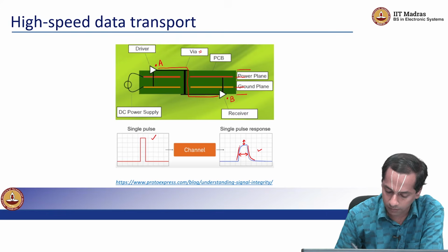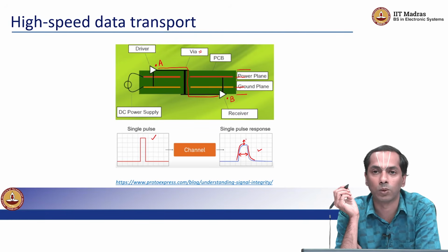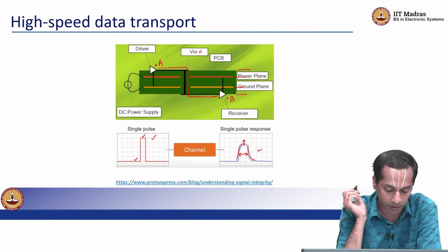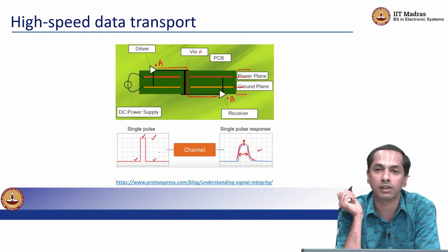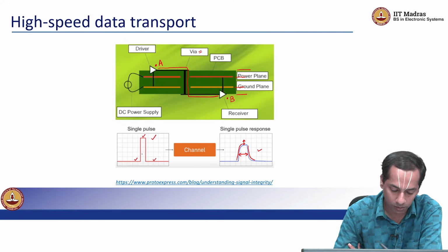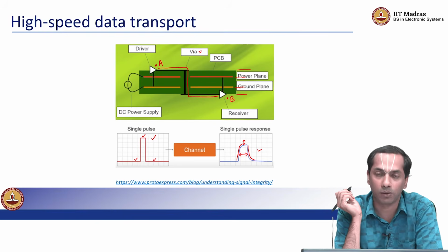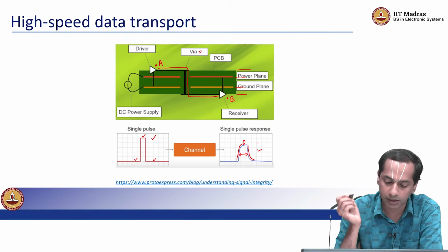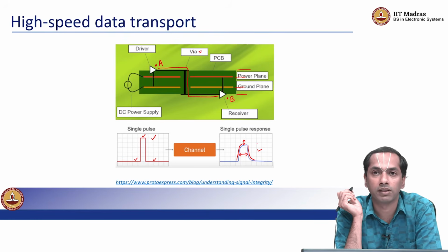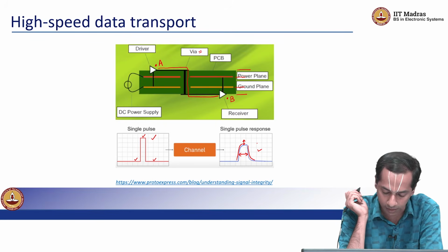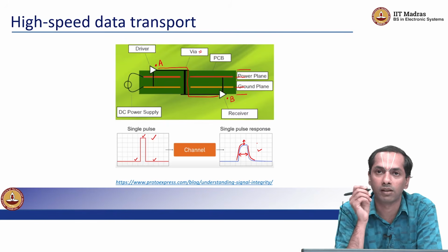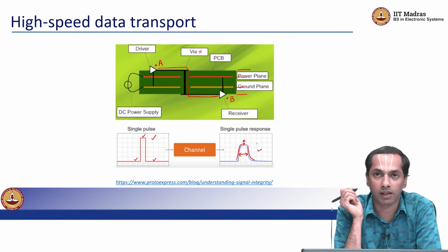it takes some time to kind of get to these different voltage levels, right. My intent was to just send a low voltage signal and a high voltage signal for a brief period of time and then come back down, right. But it seems that even though I condition my signal to make these transitions reasonably quickly at the beginning of this wire, by the time it reaches the end of the wire, I notice that it has been distorted, right, quite significantly. So, we have to understand, and we need a very simple method to say how can I understand this transformation.